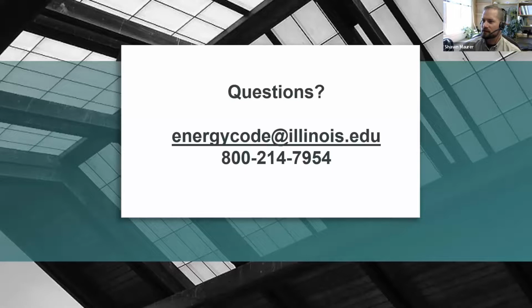Question from Gary here: is pressure testing of air barrier compliance required for both new construction and renovation of existing buildings? We touched on that earlier. It's just new construction that's required to have that pressure testing requirement.